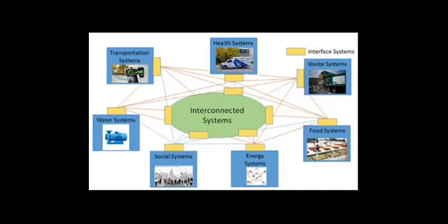Grid compatibility. Renewable energy systems must be compatible with the existing electrical grid to ensure smooth power flow and prevent disruptions. Grid codes and regulations dictate the technical specifications and performance criteria for connecting to the grid. The system must meet voltage, frequency, and power quality standards set by the grid operator. Power electronics and inverters. Most renewable energy sources, such as solar panels and wind turbines, generate direct current (DC) electricity. However, the grid operates on alternating current (AC). Power electronics, like inverters, are required to convert the DC power from renewables into AC power suitable for the grid.